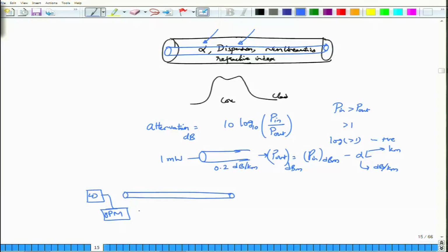It will indicate the optical power usually in dBm scale, or if you want you can also indicate it in the milliwatt scale, and you are directly measuring the optical power from the laser diode. Please note that we are not using any polarization device here, because we want to capture all of the power that is coming from the laser diode. So, this is the first step that you are going to do.